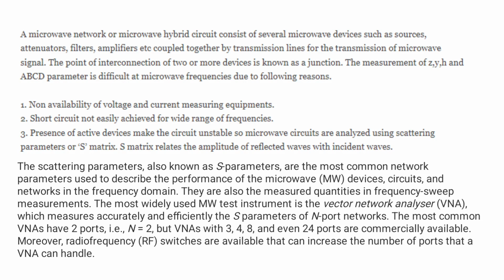The most widely used microwave test instrument is the vector network analyzer, which measures accurately and efficiently the S parameters of N port networks. The most common vector network analyzers have two ports, N equal to 2, but vector network analyzers with 3, 4, 8 and even 24 ports are commercially available. Moreover, radio frequency RF switches are available that can increase the number of ports that a vector network analyzer can handle.